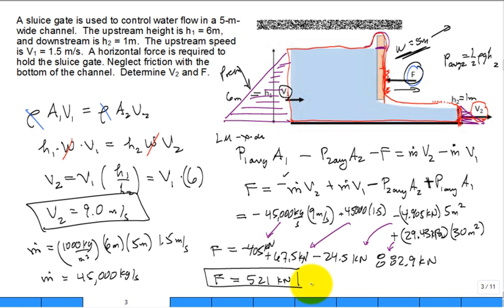What would happen if you put a hinge up here? Well, then you've got to do the moments around the gate, and it's back to statics. It's a little more work, but the net force on the gate in the x direction is that many newtons. I didn't say where it needs to be placed, or if the hinge can contribute something at the top, or something like that. We didn't do that. Okay? What did this emphasize? Spend some time getting the right control volume. If you get the right control volume, a lot of things fall into place easier, okay?